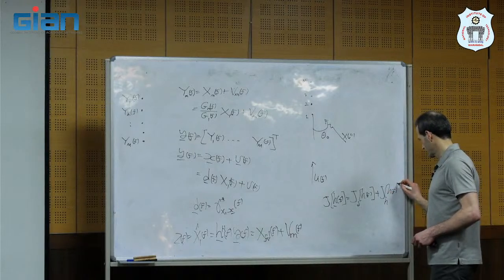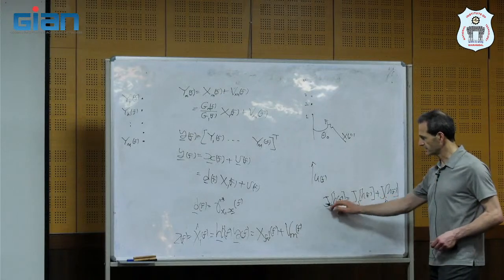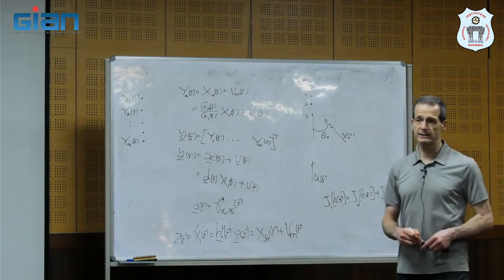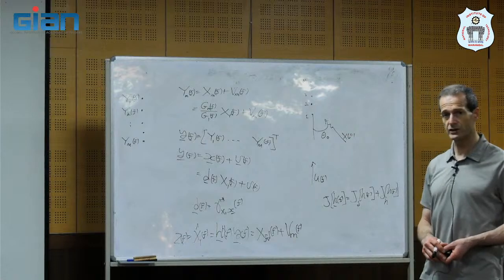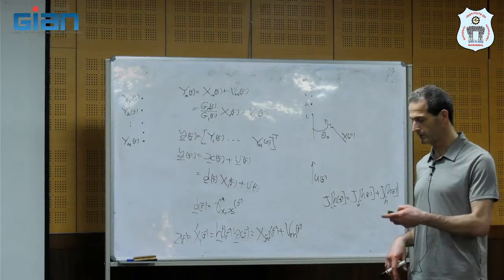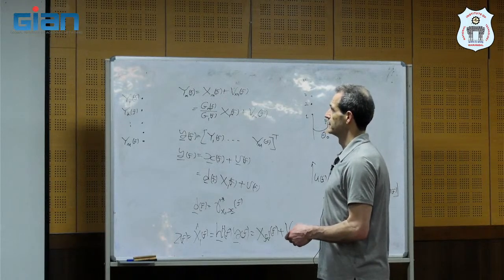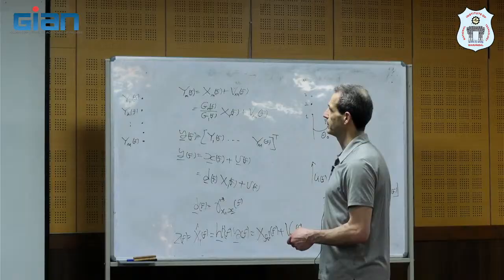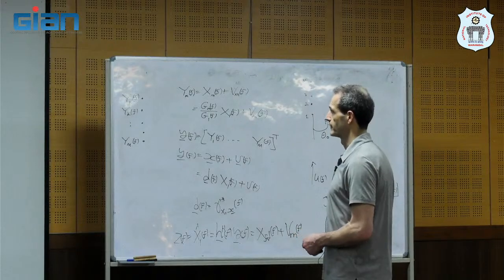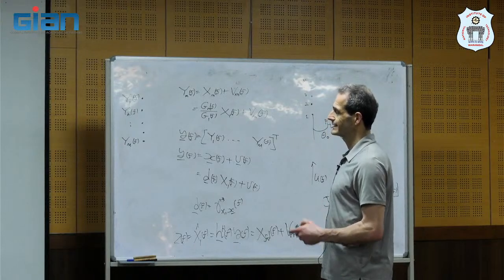One is related to the distortion. The other is related to the residual noise. So we obtained an expression for this. This is a scalar function of a vector. And we know how to find the derivative or the gradient of this function with respect to a vector and equate it to 0. And then from that, we find the optimal vector. So if we find it, we see that it looks like this. This is the vector, the optimal vector, which optimizes or minimizes the mean squared error, the narrowband.